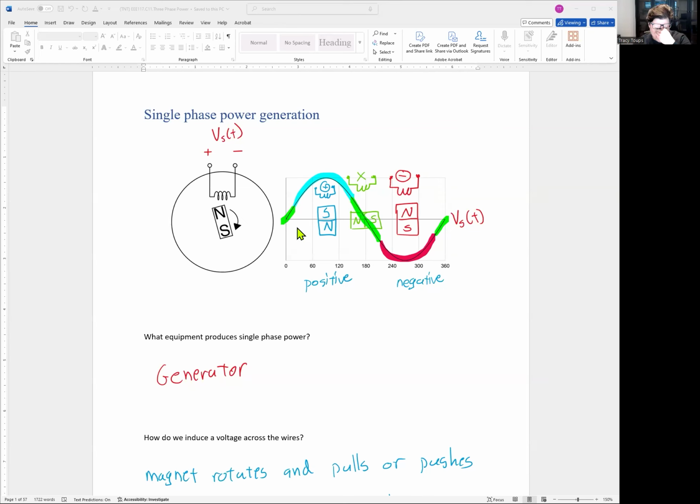By now you notice I emphasize very strongly on physically understanding what's going on, because then all the equations work out better. So a generator is a cylindrical device with coils wrapped on the outer edge. This long circular part right here is called a stator, where you have coils wrapped around it. And inside it, you're going to have a magnet that spins. Think of this like a toilet paper roll, and inside here you've got a wooden rod that's just spinning, and the wooden rod has a magnet attached to it.